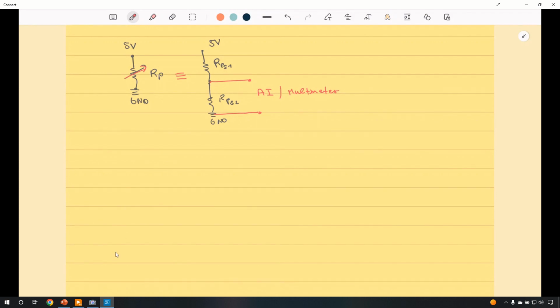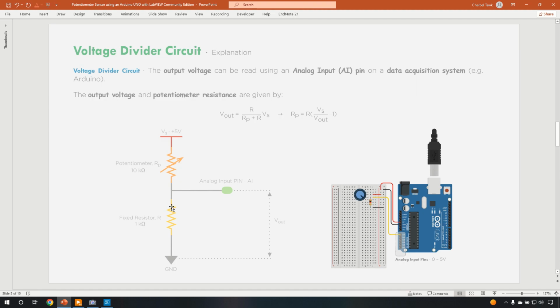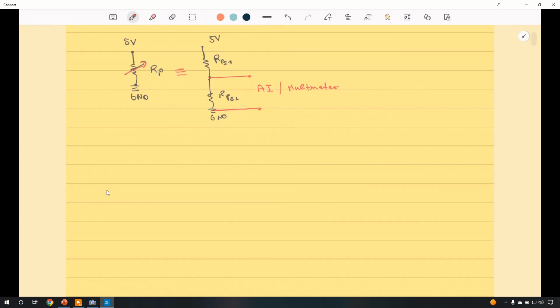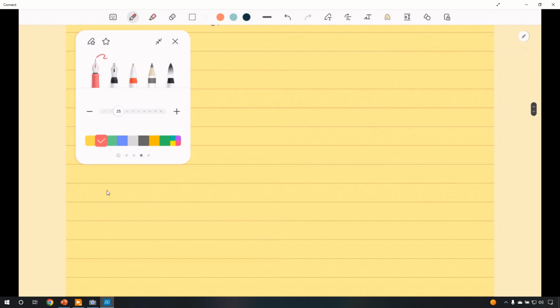Now, what we are going to do next, we are going to derive these equations by having the 1 kilo ohm fixed value resistor right here, and essentially we'll measure the output right here. In other words, this circuit is ideal for measuring the resistance value of any resistive sensor. So let us go ahead and do that. So here what we have is our potentiometer RP, and we'll use only two terminals as we will see. Here we have our 1 kilo ohms resistor. Let's call it R.